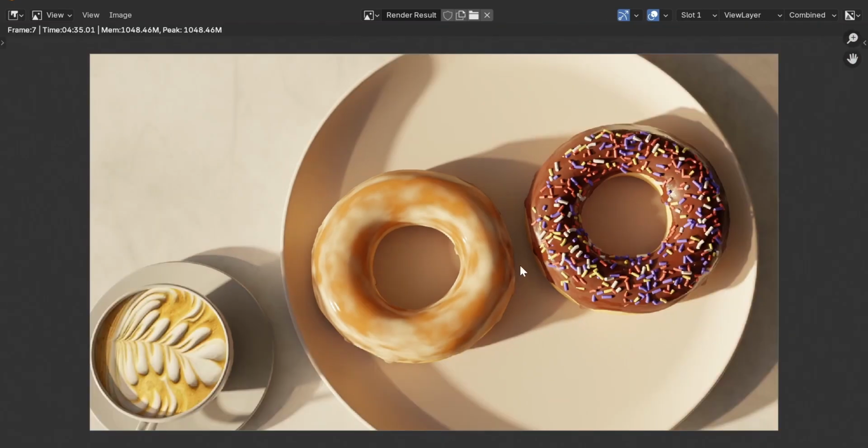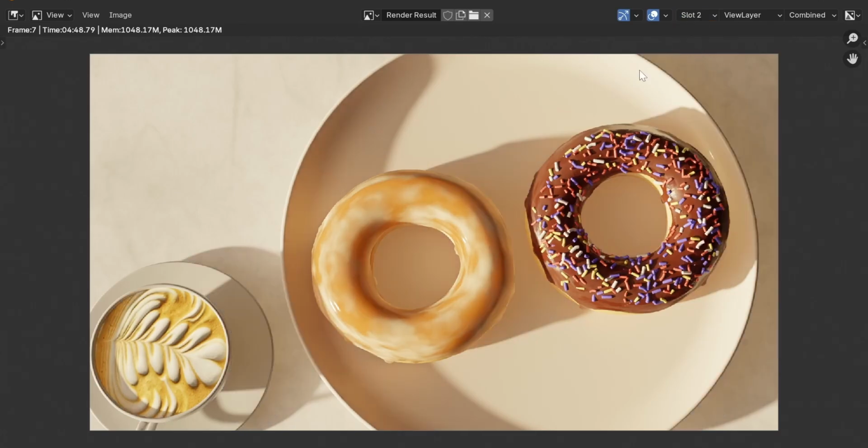When both shadows are active, the image feels less realistic because two separate shadows are being created. Even though we want combined lighting, we don't want competing shadows. Instead, we want one clear shadow from the main light and only soft highlight contribution from the secondary light. So for this setup, we disable shadow on the sunlight. Now compare image 2 and image 3. Image 2 looks cleaner and easier to read. We get that strong specular reflection and a smooth highlight across the sugar glaze. The chocolate glaze also appears creamier, which is exactly what we want.